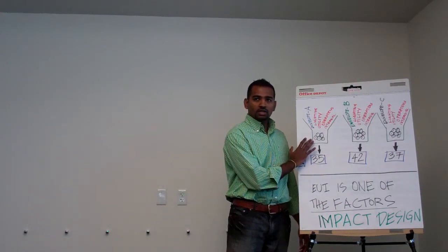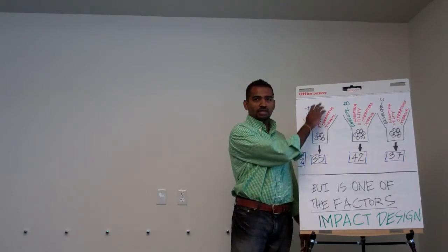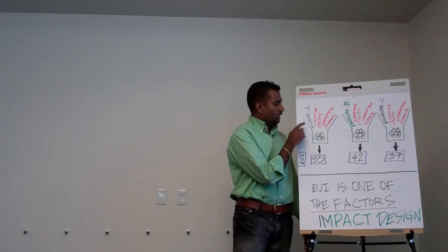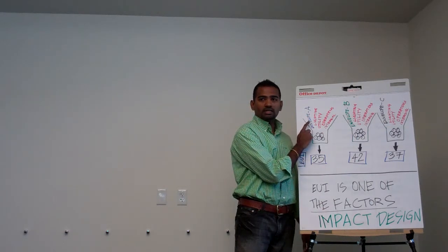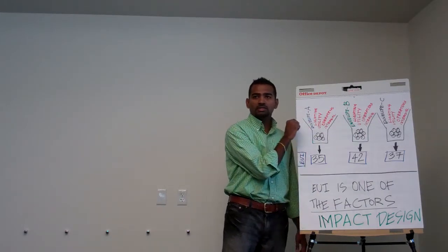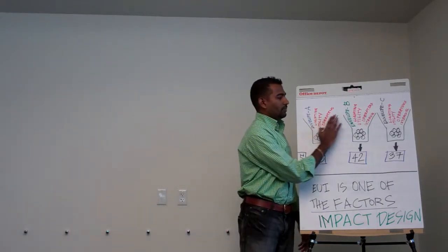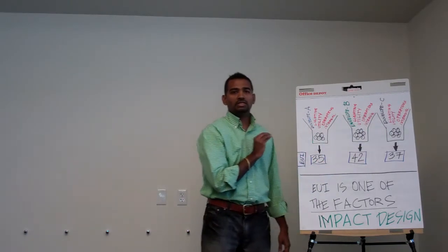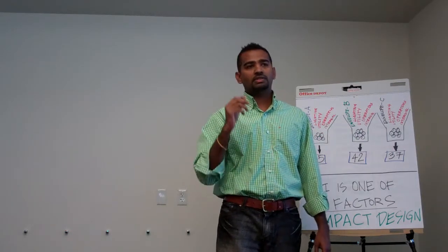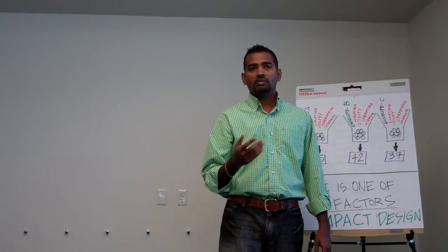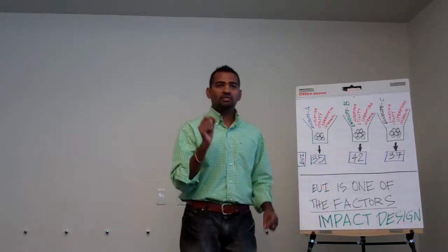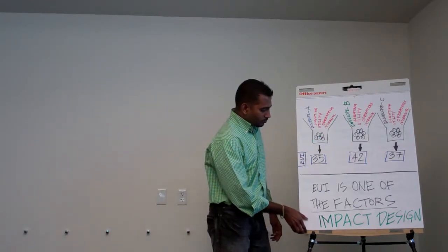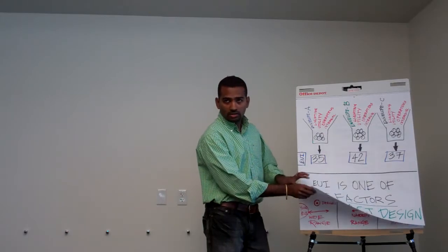So the last question on the quiz was to understand these several ingredients that go into the analysis tools, and it gives out the EUI. When we are trying to understand how one piece impacts the EUI, we have to keep the other pieces consistent across the assumptions, because it's too easy to change a couple of things at a time. It's so enticing to change it. Because it's a bunch of numbers, you can change it so easily. But if you change them all together, it's so difficult to understand what's going on. Which one had the impact? Was it the lighting or the envelope that you changed?